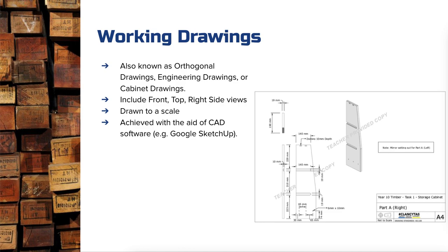Working drawings you should be very familiar with. We do them in SketchUp. We add a title block. The title block has name of the project, name of the part, the person who drew it, probably the date that it was drawn, some details around whether it's on a scale or not. But the primary bit of information here is shape and dimensions, and enough detail that you should be able to put those measurements onto timber in the workshop, make some cuts without making any mistakes at all, and your project should come together as a finished product.